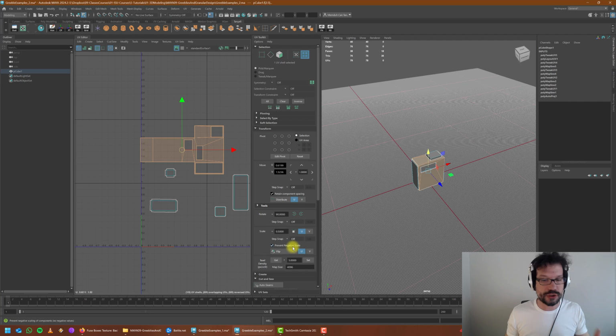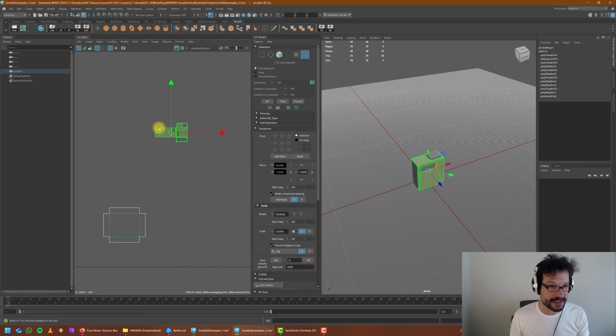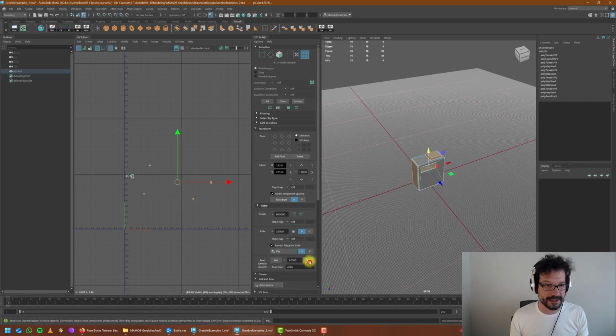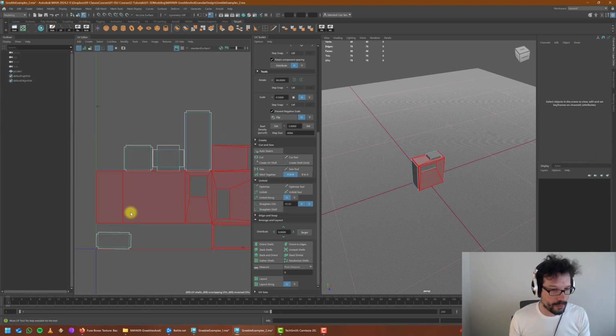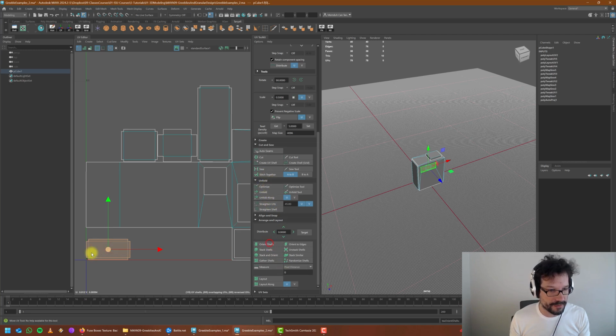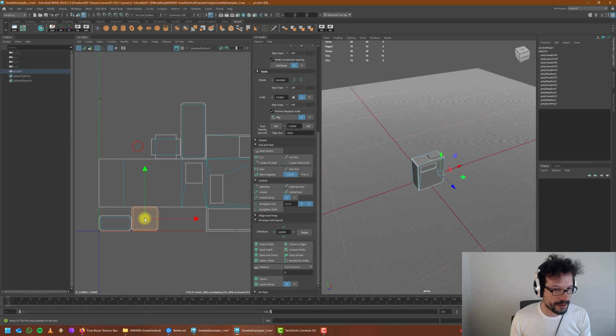So thinking about that, let's assume that we're going to use a 4K texture, and right now this is incredibly large. We are allocating more than 50 pixels for just 1 centimeter, which is an extreme amount of detail which we won't need. So instead, we can say, okay, for each centimeter we're going to have 5 pixels. Okay, so if we set that, there we go, this is the amount of space that will be allocated. Okay, and we can gather them together, lay them out like so. Maya will automatically suggest laying them out like this. Maybe we should orient this better. Okay, you can even go ahead and start optimizing stuff just a touch, you don't need much.